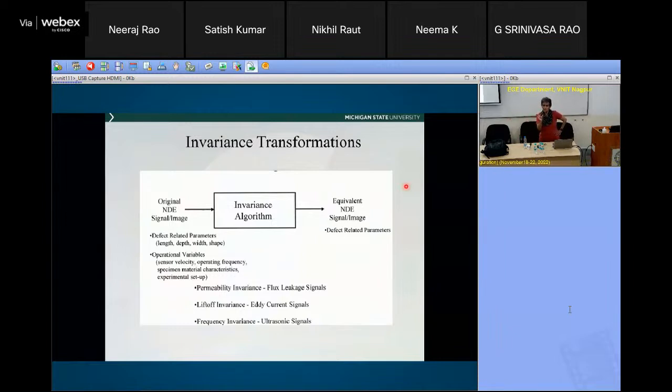If it is really a 20% defect, the remedial action is just to reduce the pressure of transmission. But if it is 60 or 80, they will put a sleeve around it at that area. So they don't care about exact size, they just want you to classify. That's the reason that we classify.